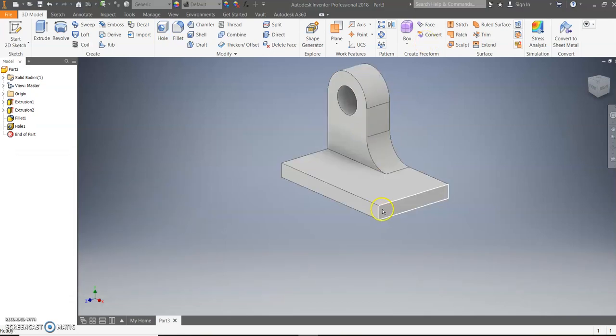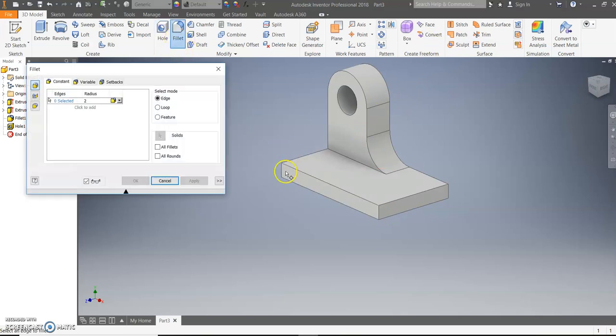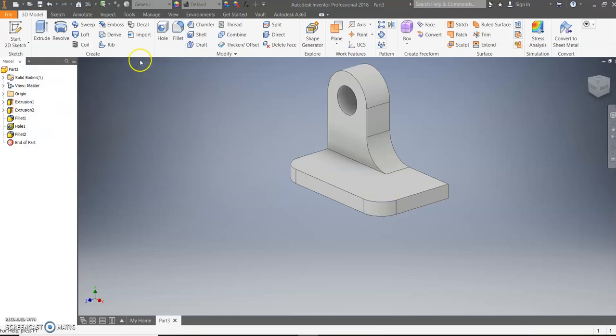Now I need to work on the lower portion. On the lower portion, first I'm going to fillet these edges. I'll click on these edges down here and fillet them. Just 2 in this case. And now, if we look closely, it's going to be a 1.5 radius. So they're not quite as steep as our upper one. And then I'm going to hit OK.